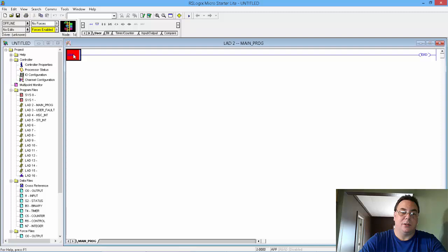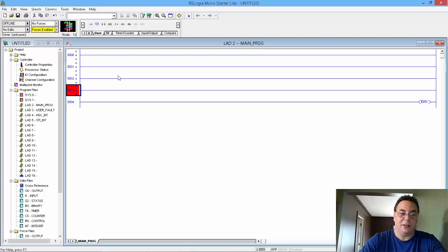Okay, so we're just going to select that by clicking on there. And here, up under the User tab, these are the tools under the User tab. These are tools, timer on, timer off, return a timer, and so on, under some other tabs, but basically we're going to be staying here in the User tab. And under that tab, we're going to select Add Rung. Okay, just throw in a few rungs just to get us some room to work here.